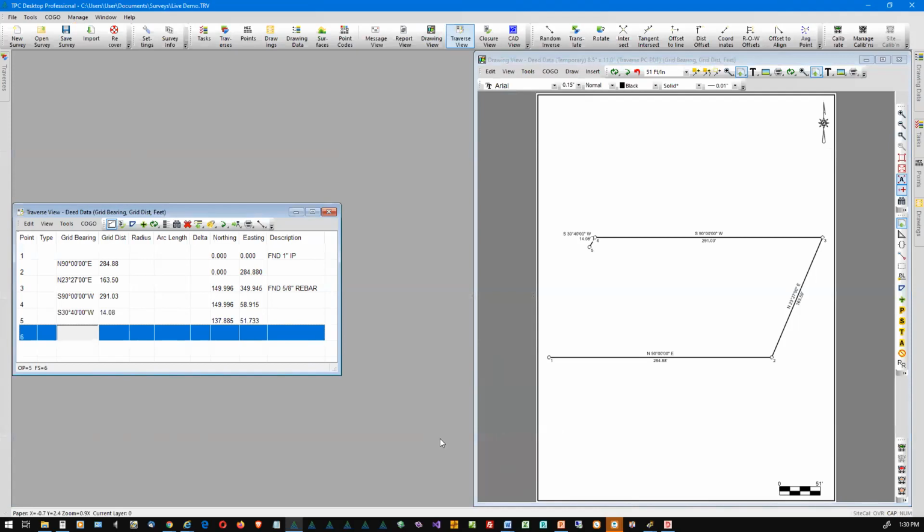All right, so let's go ahead and enter this. What I have is curves. There is a chapter in the alignments learning guide on horizontal curves, and there are a lot of ways to do curves. In this case, I have the chord bearing, the chord distance.